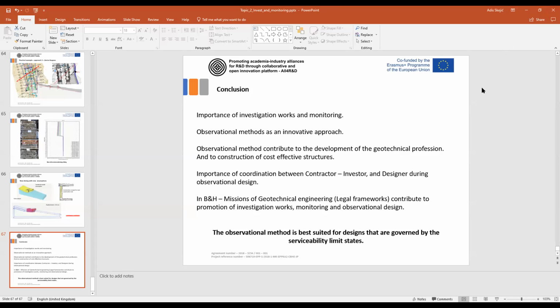So when designing a highway, if it's, for example, 50 kilometers long, does it mean that every 200 meters there has to be a borehole? That's right. At least that's the minimum of the minimum for the main design. If you have a 10 kilometer road, you need to perform a borehole at least every 200 meters. Do you mean it's enough or it's not enough? Or it's too much? What do you think?